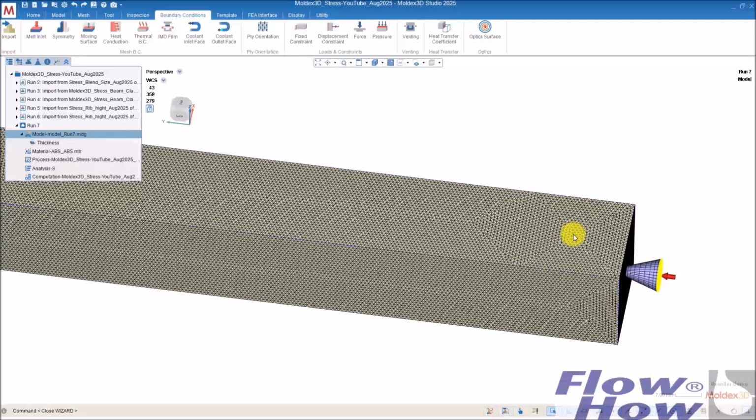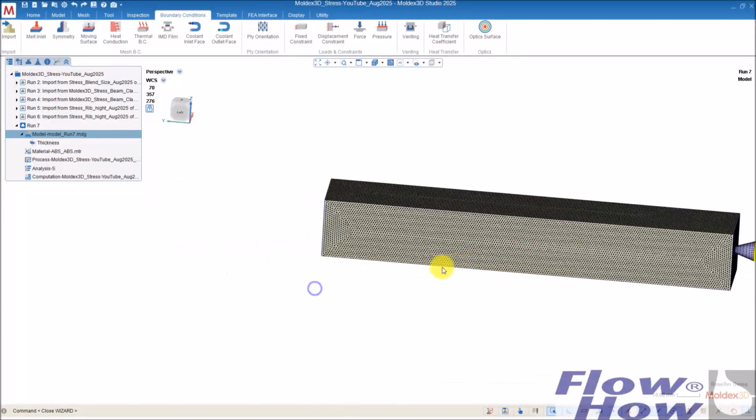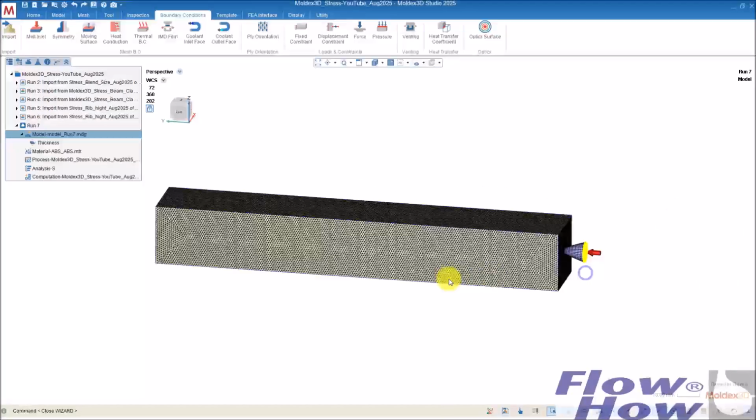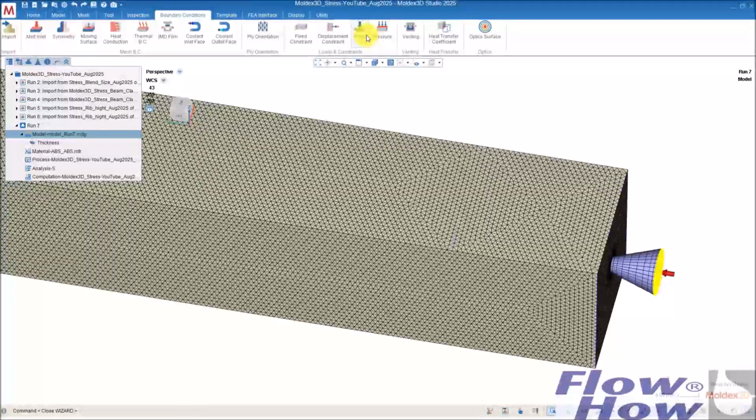If I want a force of 1 kilo hanging downwards out here and clamp it totally here, then I can choose a force, but I have to count the number of nodes in the area, and then I sum up the forces that I put on each node.